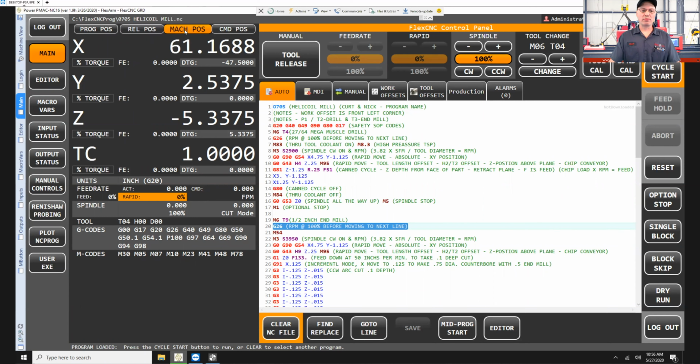Machine position, that is from your home position. So G53, if you wanted to go from halfway down the machine, so you can actually have op 1, op 2 pendulum mode. You want to get the machine out of the first zone, but not quite into the second zone. You can kind of stop it halfway in between, and that would maybe be a G53 X 120 inches on a 20-foot machine. So it moves down to that point. It's referring back to the home position.